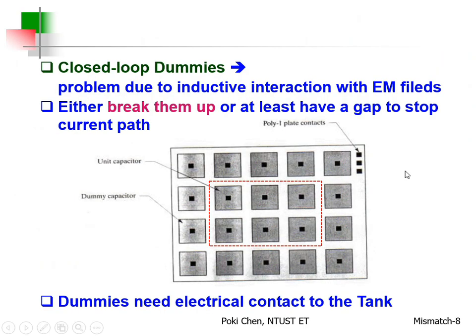And how about capacitors? Oh, this is a very good example. Actually, it is a really bad example. But you can see from the very beginning, we have 6 capacitors to be protected by dummies, right? And how about the golden rule for dummy? The spacing needs to be the same, right? So, it looks very good. So good to be true. Too good to be true.